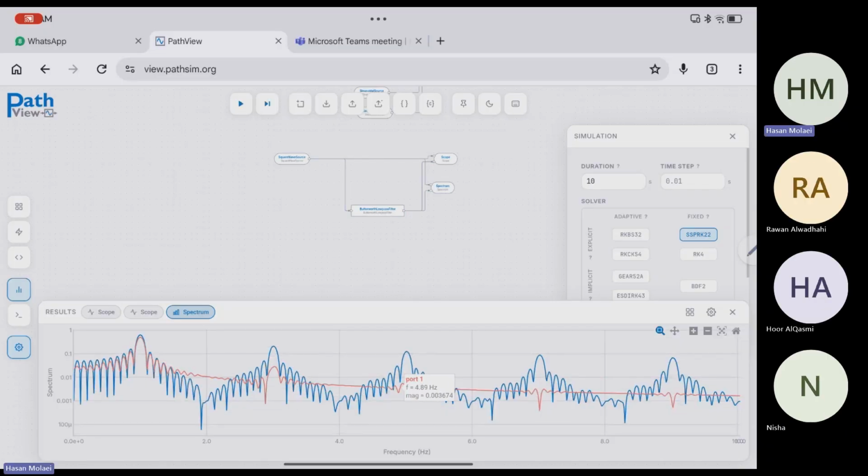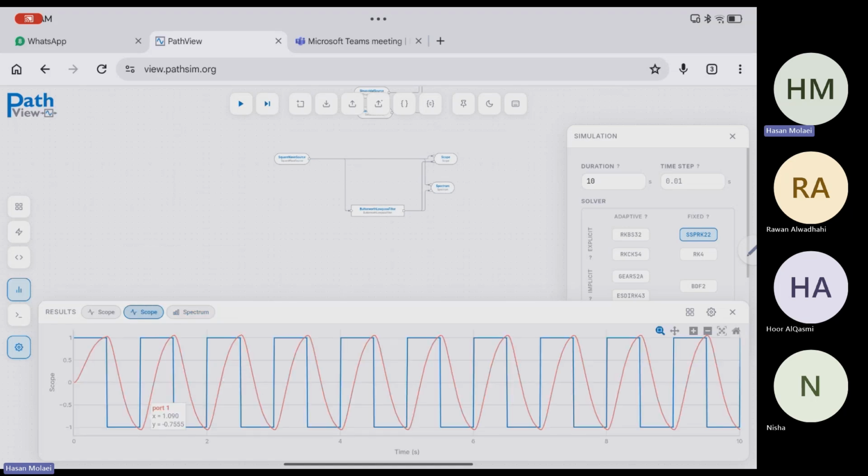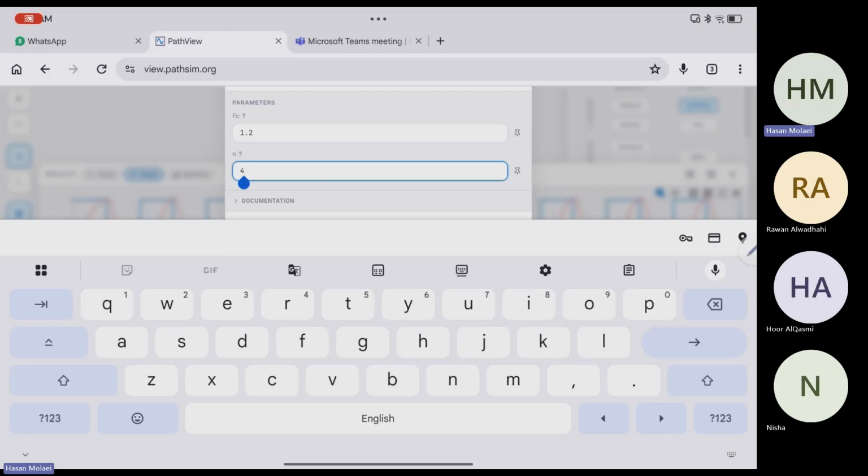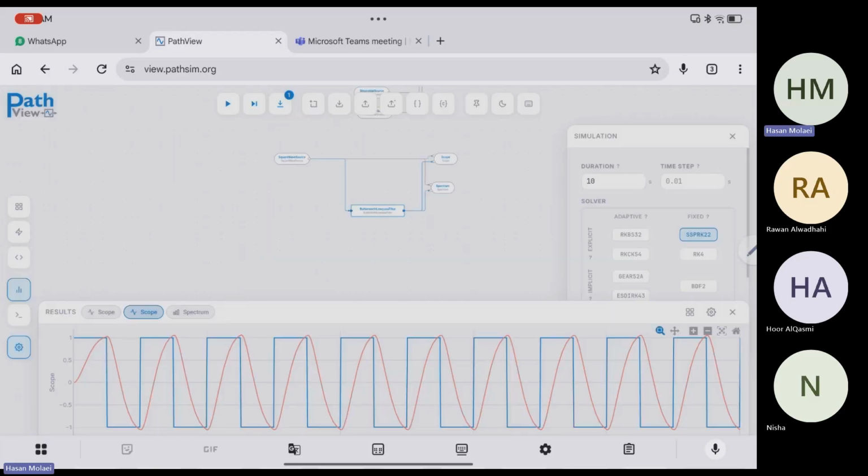You can see we don't have these peaks anymore. But the first one, we still have it. See, it's going to be something like a sinusoid, but since this filter is not perfect, let me increase its order. If I increase to 4, it should be better.